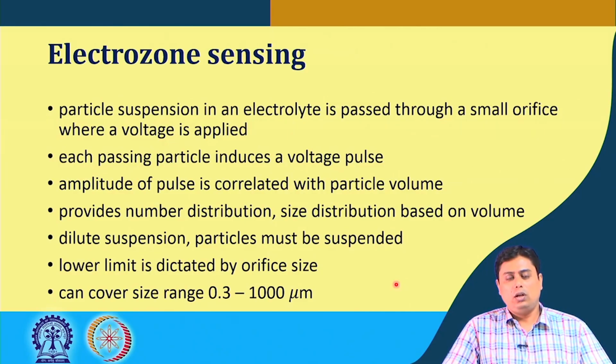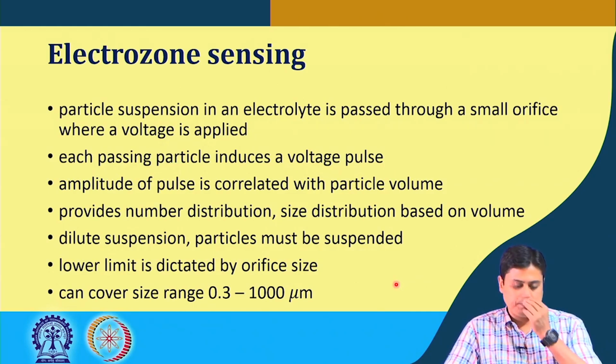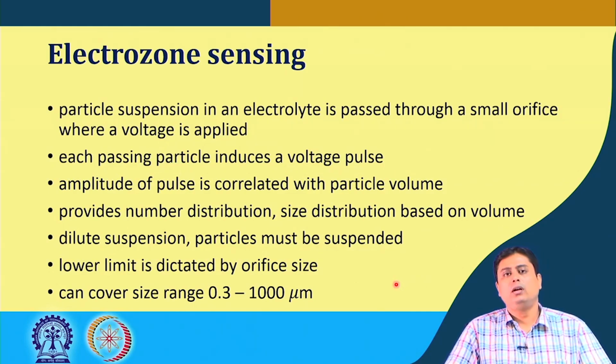Now, the lower limit of the linear dimension that you can achieve by this methodology is dictated by the orifice size, that is, how small your orifice is will be the size of the lowest size particle that you can determine. Typically, it can cover the size range from 0.3 to 1000 micron.